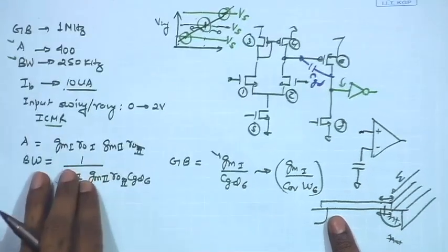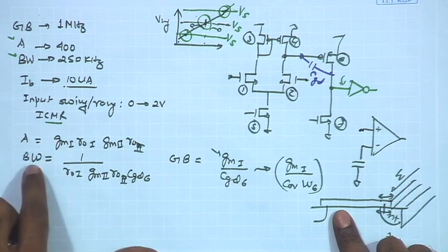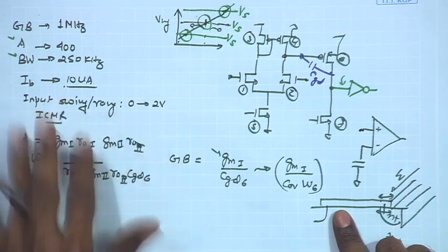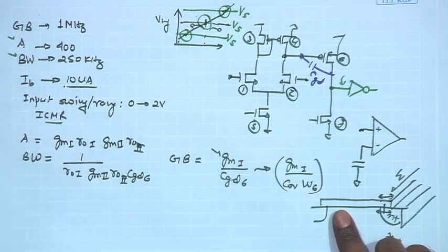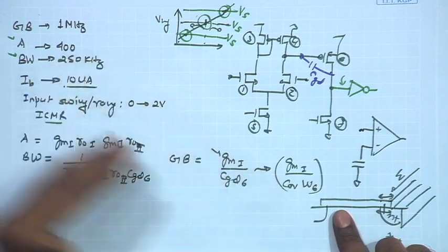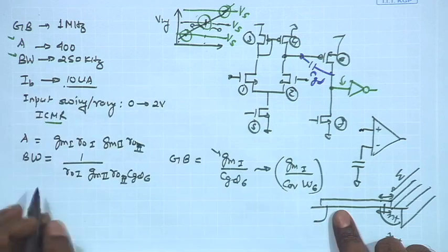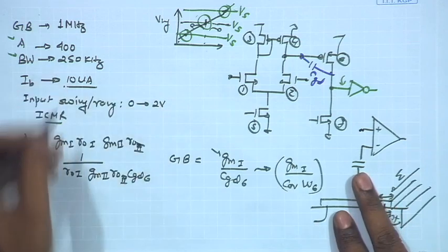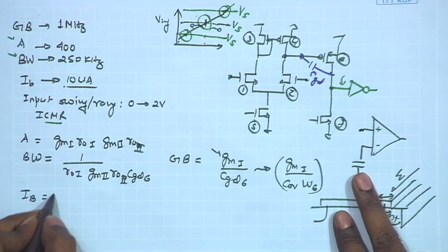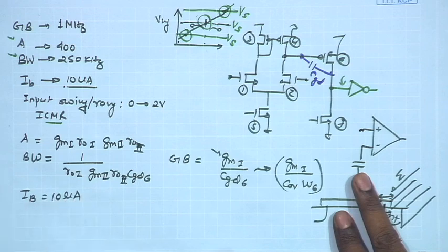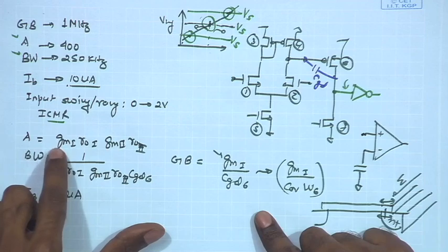and we have also the dependency of the gain and the bandwidth individually. So, these can be the equations which are going to govern our design steps. Based on this, we can iterate with a given starting point and try to see in which direction to move. So, I can start with a bias current budget, say IB equal to 10 microampere, and for that I have the overall gain to be determined.